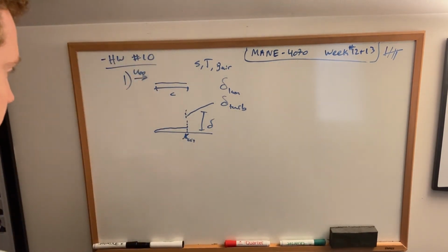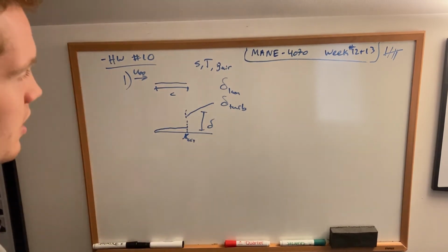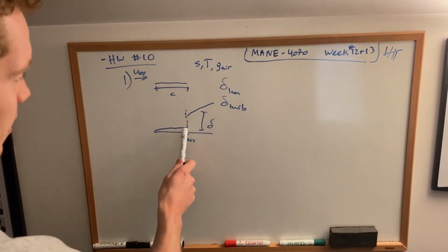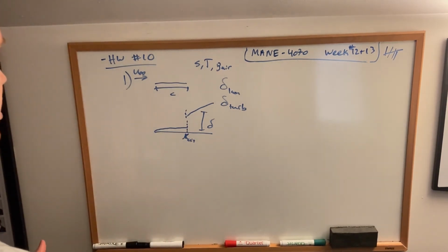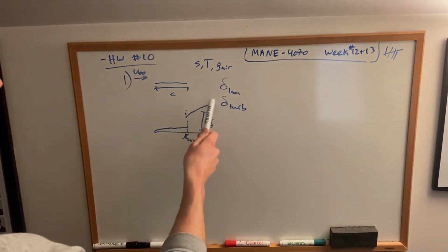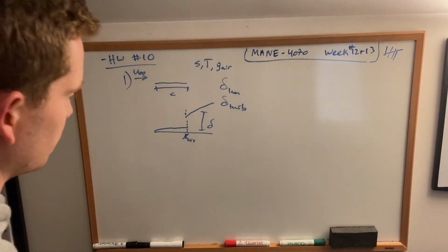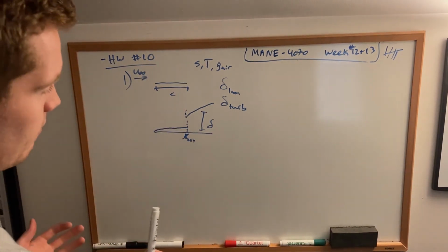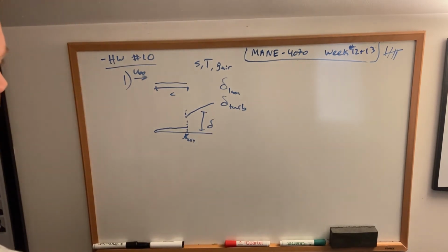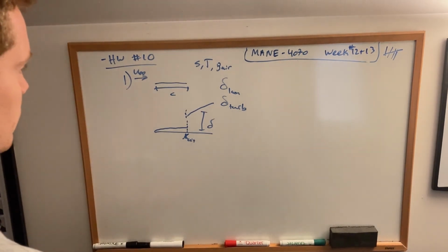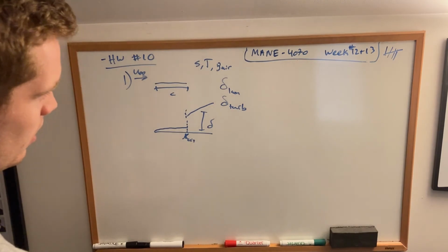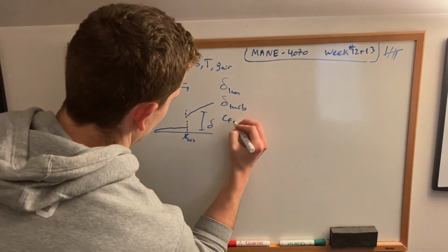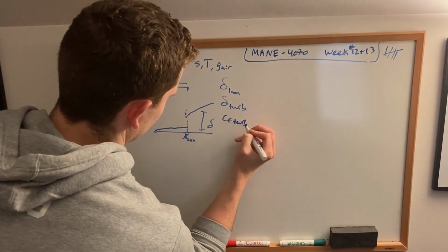Before and after that, if this is the laminar regime, you're going to use your laminar boundary layer equation to plot that boundary layer shape, and then I'm asking you to connect that to your turbulent boundary layer shape. So you have to determine where, or if, you go critical, and plot the shape of your boundary layers from there.